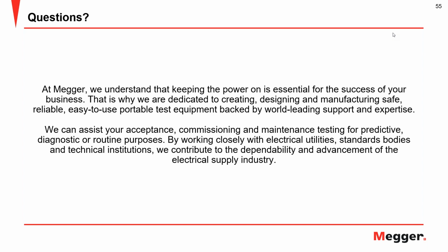So if your inception voltage is above the operating voltage, one may think that everything is okay and all is well, and more or less that's true. But if the extinction voltage is lower than the operating voltage, then, as Dennis pointed out and as Robert mentioned earlier in his presentation, switching or a lightning strike, something that causes a transient in your voltage, then exceeds the inception voltage and you have partial discharge start to take place.